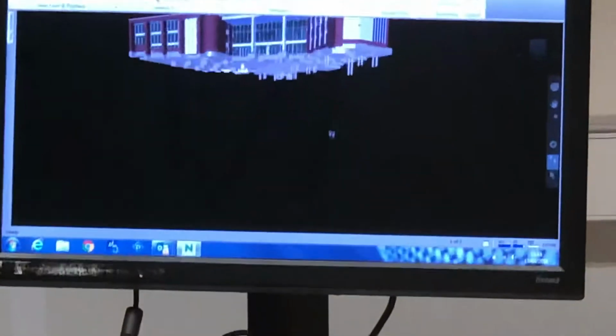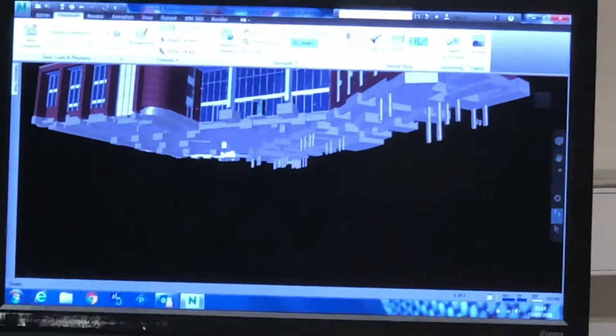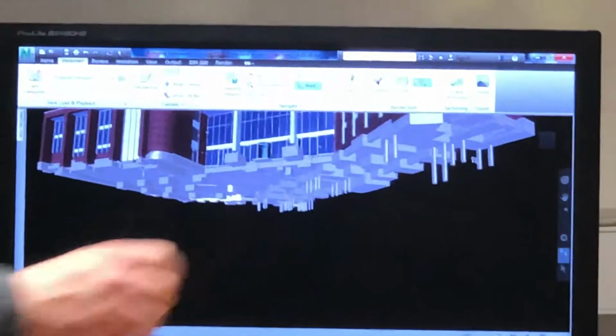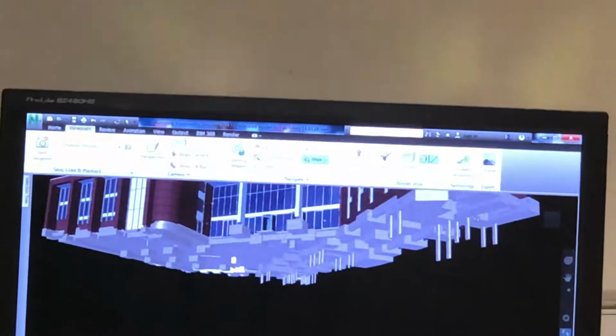What you guys are going to see out on site, what we do is we come down to the level where you're going to be. We'll put it upside down. We're in the groundwork stage, so if you can see these elements here, here and here, there's 3 cores on the edge of the residential building, which act as tension cores for the building, so that's what keeps everything down.